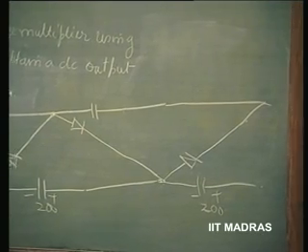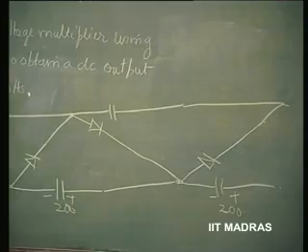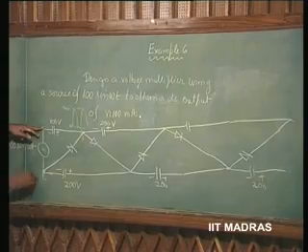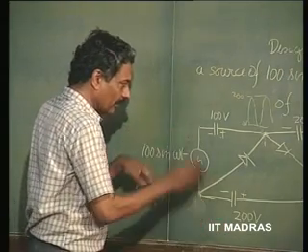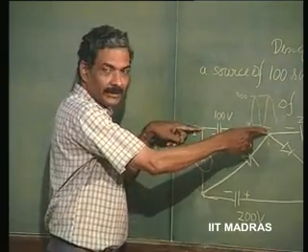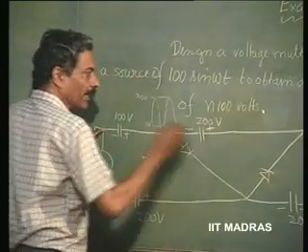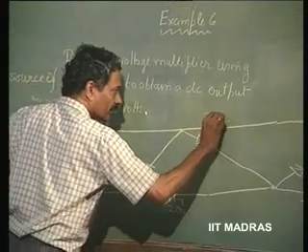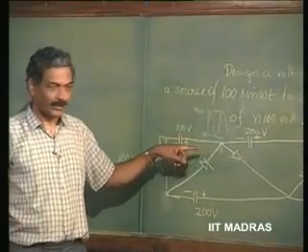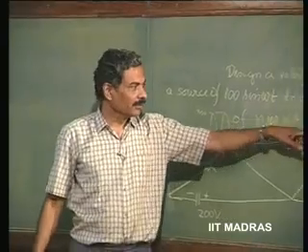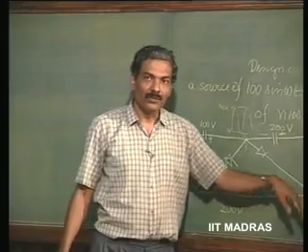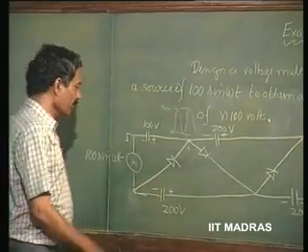So n times 200 is what is got from this terminal to this. Whereas you can see here, if this is not grounded, if this is the common point, then the same circuit will give you 100 from here to here and 300 from here to here, and again this will be minus, and this will be 200, 500 from here to here. So all the odd voltages, 100 odd multiples, 100, 300, 500 can be got with this as common point, and even ones 200, 400, 600, 800, and so on can be got with this as the common point.